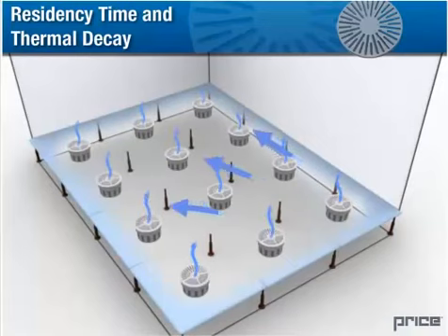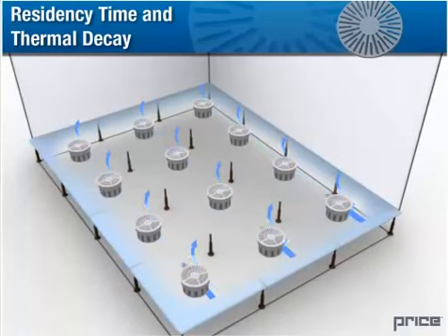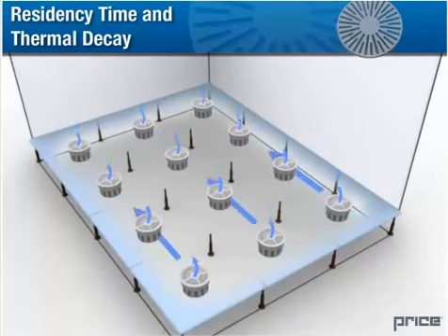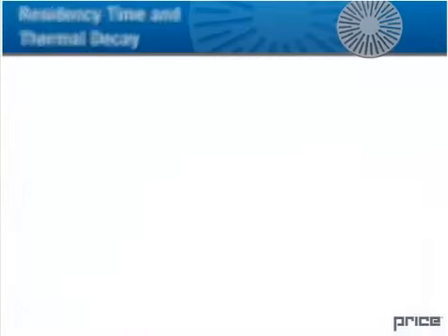It is recommended that the air be spread out when it's discharged into the plenum by using inlet directional vanes or multiple points of injection. This way, the formation of circular patterns in the plenum can be avoided. It is important to promote the even distribution of air in the plenum and the ability to direct more air into local areas of resistance so that consistency in airflow can be achieved.